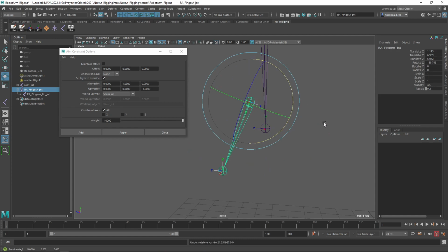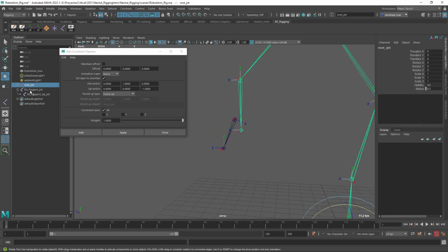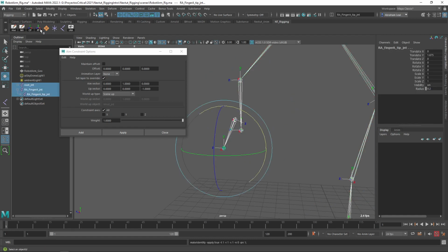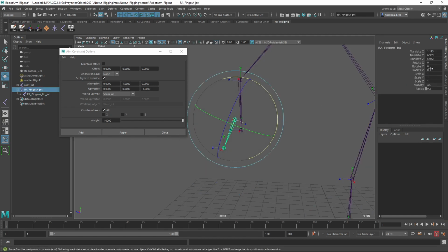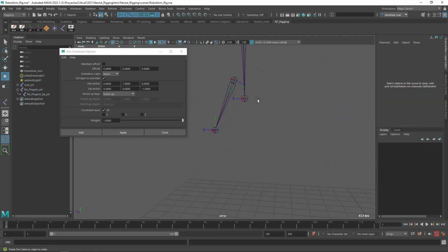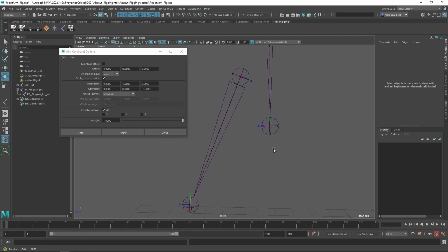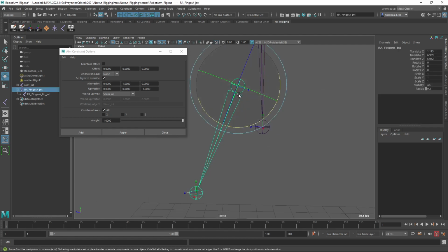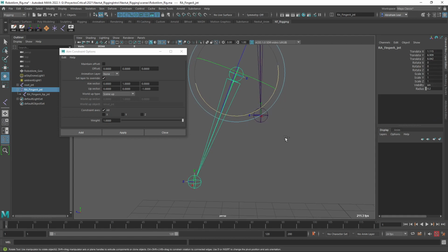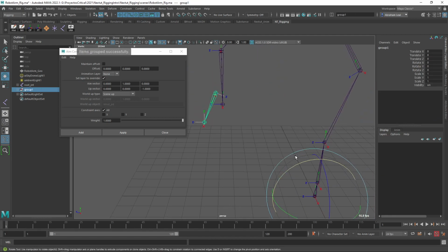And as you can see, this is going to be a very clean movement. So I'm going to grab all of the fingers and I'm just going to freeze transformation. So that, again, every single rotation, everything is clean. Very important that we do that. And I want to keep this same orientation but duplicate it towards the other parts of the characters or the elements. So what am I going to do here? Very easy. I'm going to grab this joint chain and press Control G to group it.